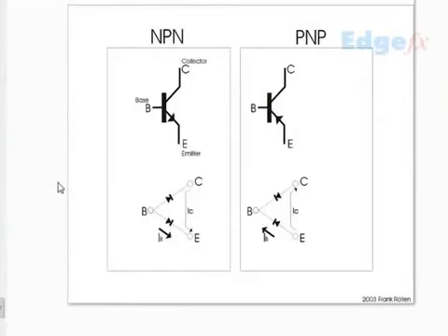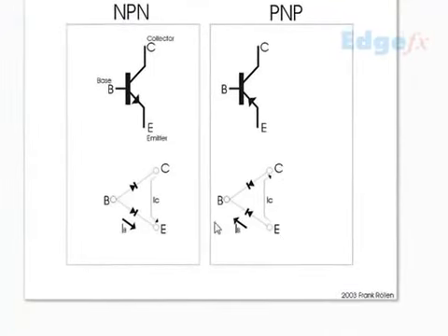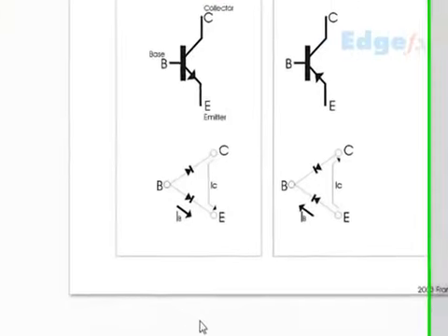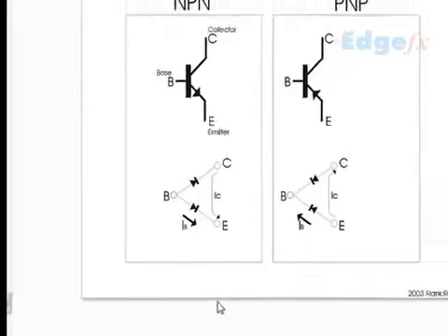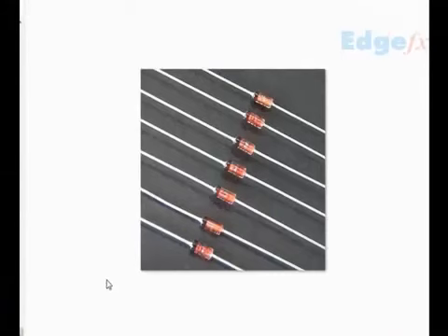Remember, this is the only way that you have to test transistors. That means for conduction in NPN, base to emitter and base to collector, and no conduction between collector and emitter. And in the PNP, it is emitter to base, collector to base, and no conduction between collector and emitter. This is the only method of checking a transistor. It should always be checked after taking it out from the circuit, or if it's a new transistor, you have to check it this way only.